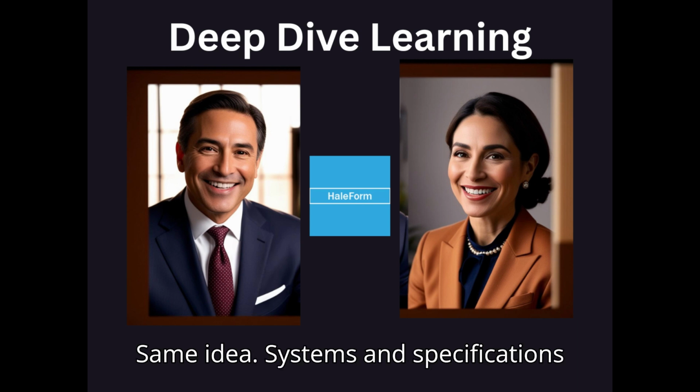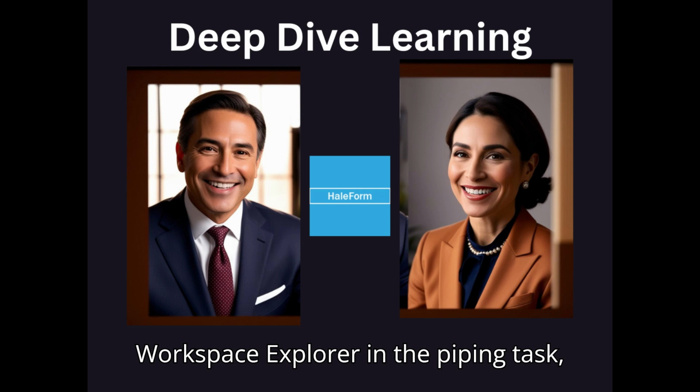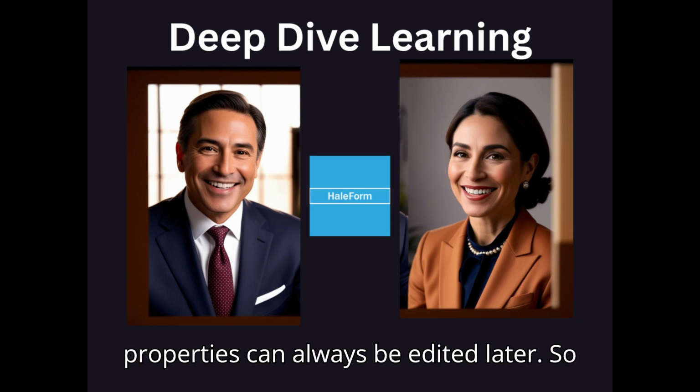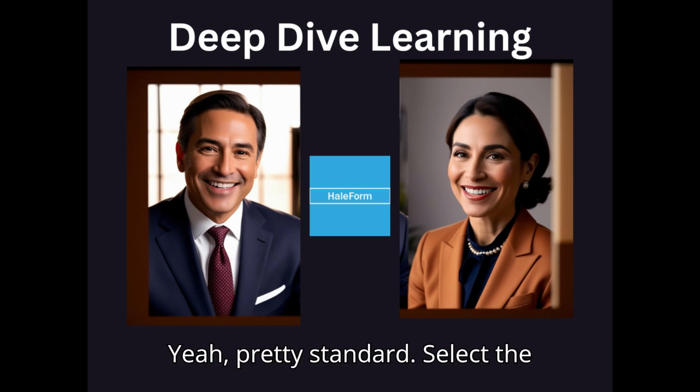Systems and Specifications task using the ribbon command, where you define description, fluid requirement, type. Or via the Workspace Explorer in the piping task, entering similar info. And again, properties can always be edited later. So flexibility on where you create them. Editing properties is straightforward. Yeah, pretty standard.